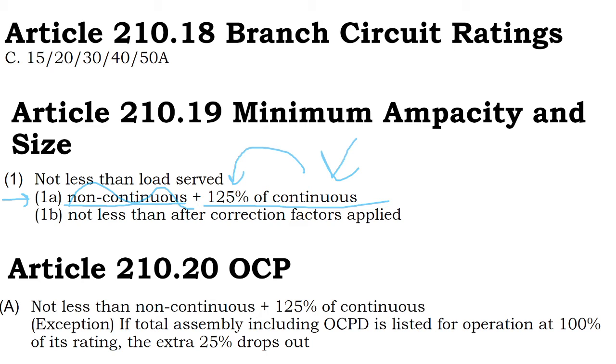And so a good rule of thumb for any electrician exam is just to take the ampacity requirement of the device, multiply by 125%, and you're at the ampacity size for the wire, and then you either round up to the nearest breaker or down to the nearest breaker, as we'll see in a minute. Now, specialty devices like solar may have additional ampacity requirements. We're going to be talking about that more tomorrow in our solar specific class.